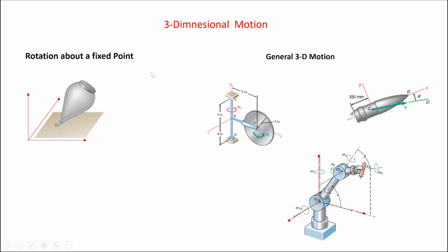In three-dimensional motion, for example, this is a top, which you are aware of, and which is really a 3D motion, because it is spinning about its own axis as well as precessing about a vertical axis. You know very well, so here it's not a plane motion. It is a fully three-dimensional motion. Every particle is having a 3D motion, and they're neither parallel nor pure translation.